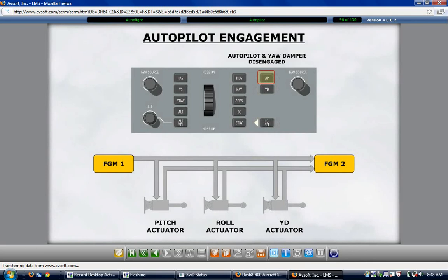The autopilot will engage if AHRS-1 and AHRS-2 are valid and in agreement, ADC-1 and ADC-2 are valid and in agreement, and the aircraft is airborne at an attitude within the limits for engagement. Selection of the manual pitch trim disconnect switch or the autopilot disengage switches prevents engagement.